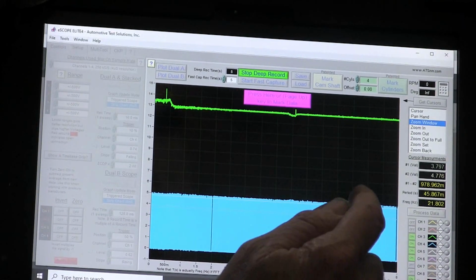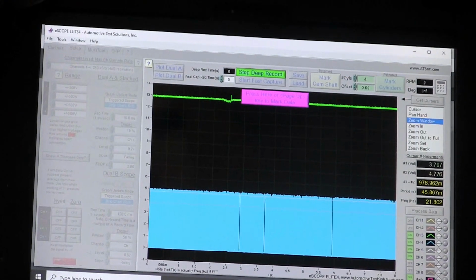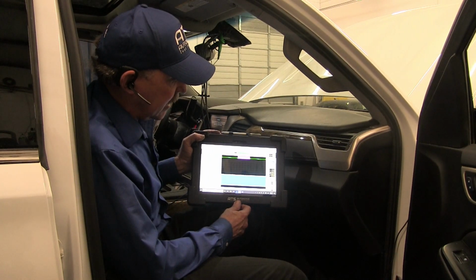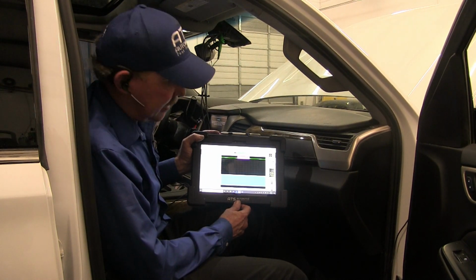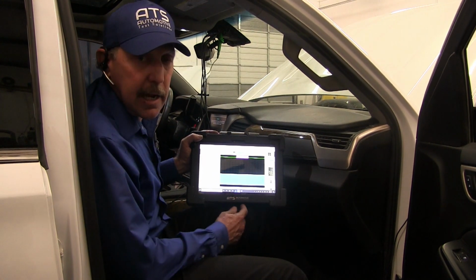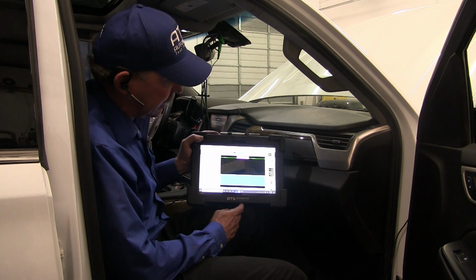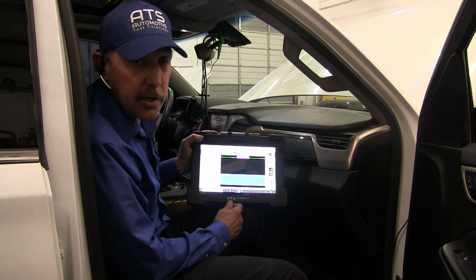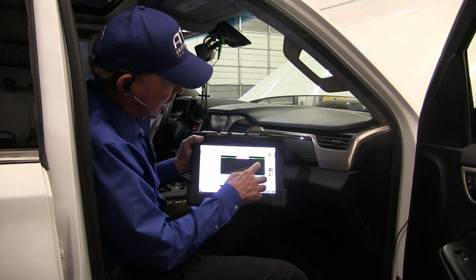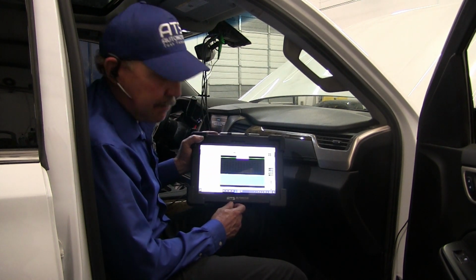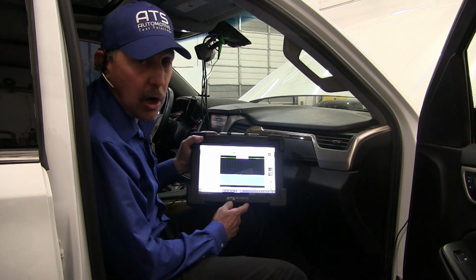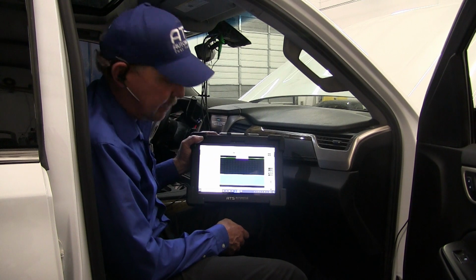This line is going to have a 10.5 to 11 volt message, and that's going to tell the system that it's ready to go to sleep. The enabling line here is enabling and turning on the CAN system. The LAN system is turned on by messaging within the system. So we actually have two different enables to wake up modules. One is done on the bus, and one is done with a hard wire where I have voltage that comes up.